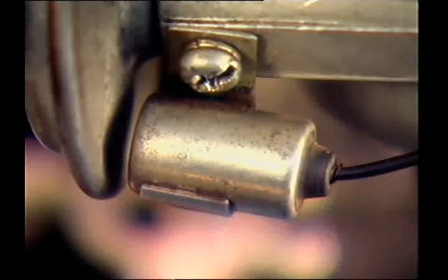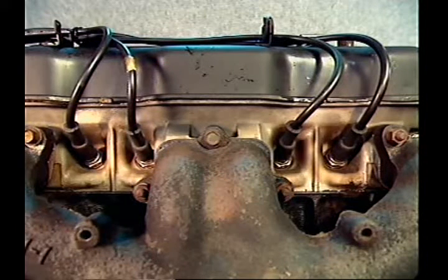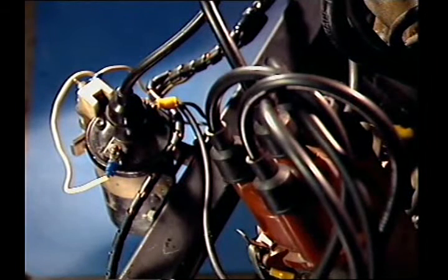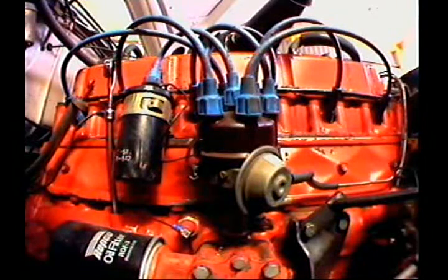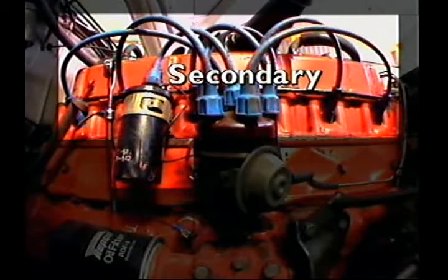the cycle. A capacitor, to assist in the rapid collapse of the coil's magnetic field. A distributor, to house the contact breaker and distribute the high tension voltage from the ignition coil and spark plugs to ignite the air-fuel mixture in each cylinder in the correct firing order. Connecting wires and leads suitable for conducting the current flowing in the system at the appropriate voltage level. When these components are connected together, they form two distinct circuits, primary and secondary.